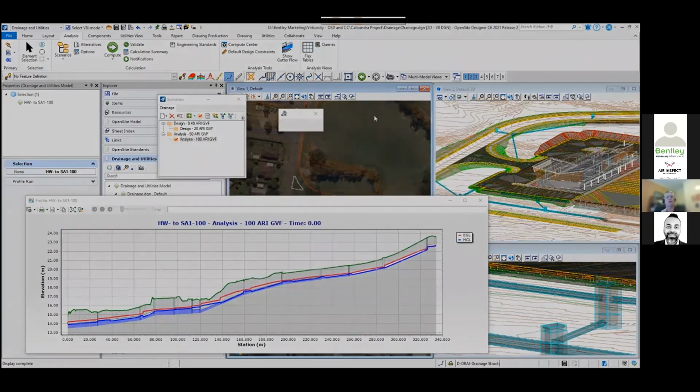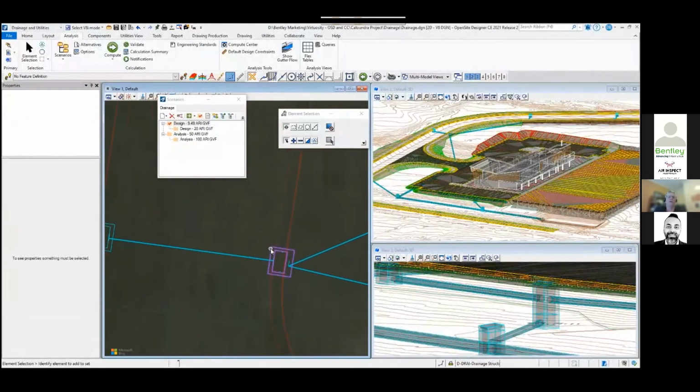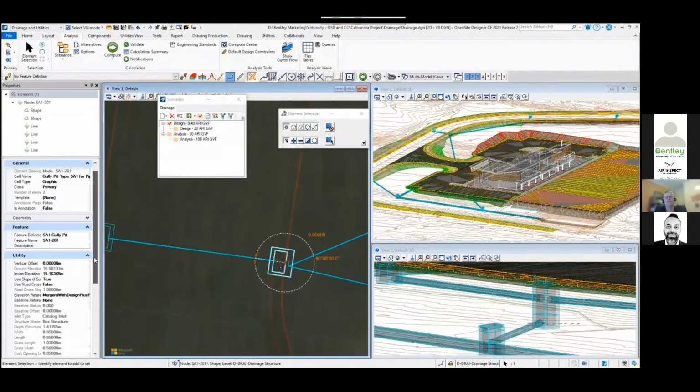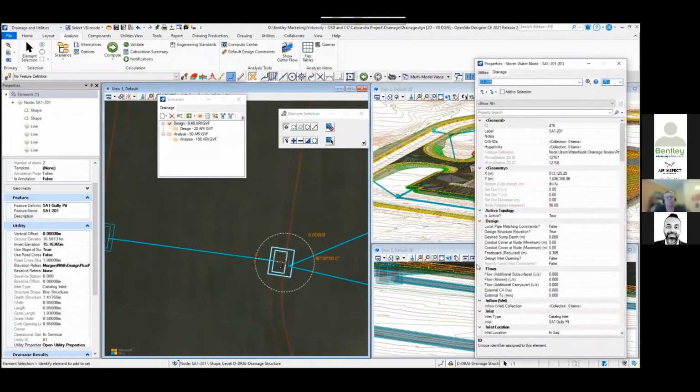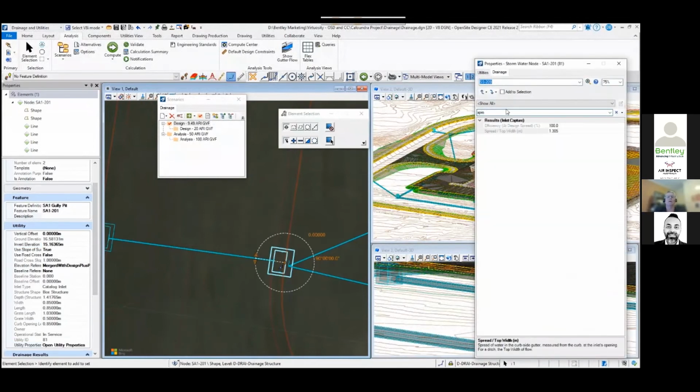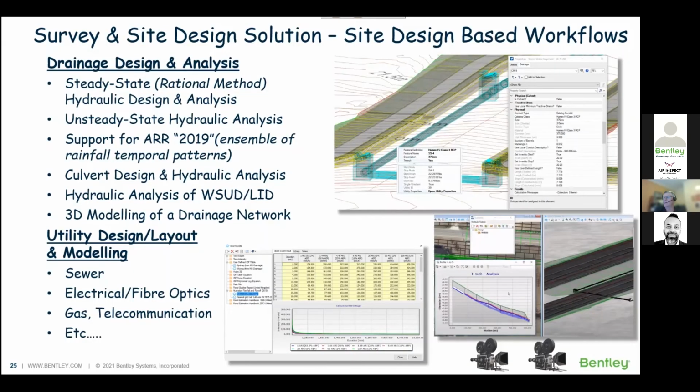So given that, we're going to move forward with this drainage design. This drainage design might take a couple of days, and we're trying to roll this all into 10 minutes. But we've identified that pit that flagged to say that the spread width was beyond the minimum threshold. And one of the things that we could do in there is highlight that particular pit, and we might want to swap that out. We might put a double pit in there. We might do something that allows us to take that water into that pit a little bit more effectively.